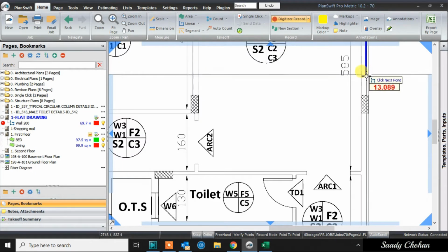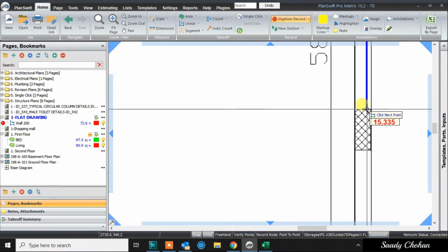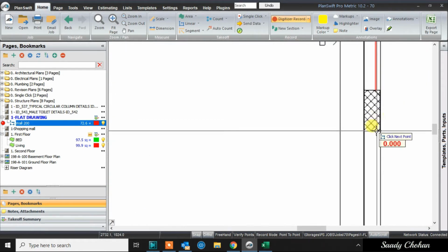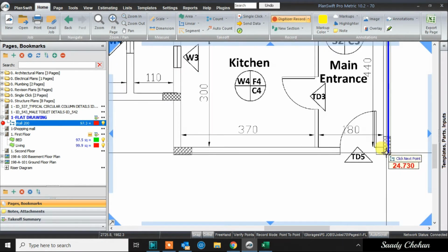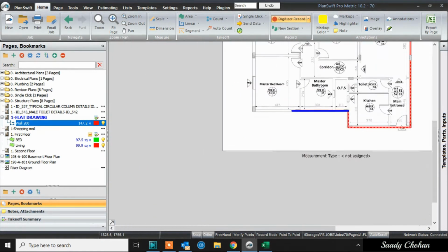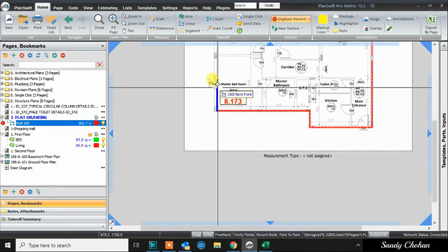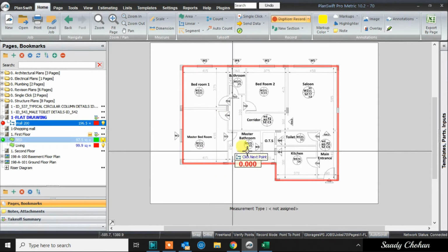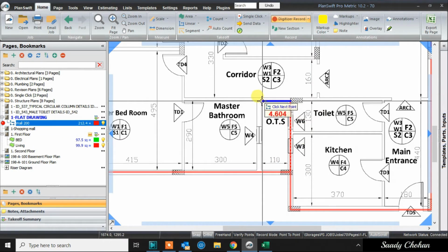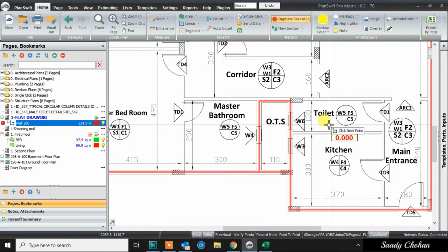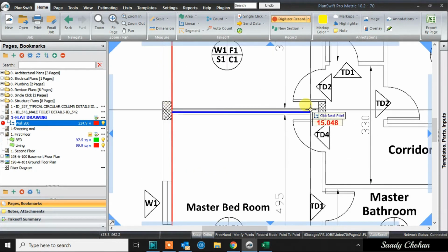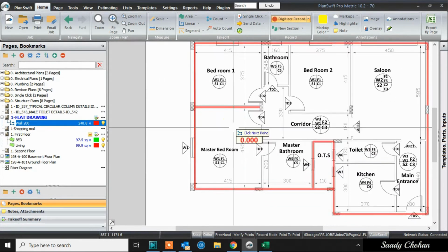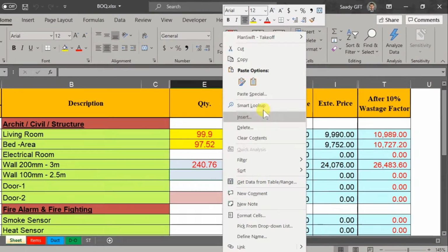While highlighting, you may find you need to stop here beside the column. So double click to make the cursor free, and now you can add one more. It starts from here and keep adding. Concept is highlighting. The way you highlight, total value will be with you. Okay, 196. I find out something I missed. I can add more. Double click, cursor is free. Okay, it's here. I think I have done all the wall 200. I can right click and stop. And you know better, quantity is already there.